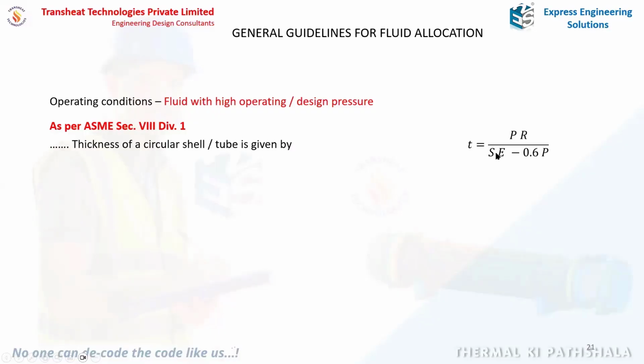For a given material and temperature conditions, stress value is fixed from the code. Joint efficiency, based on your quality NDT, you can decide, that's fixed. Your pressure is fixed. It's only the radius. So thickness is proportional to radius. The higher your radius or diameter, the higher your required thickness.